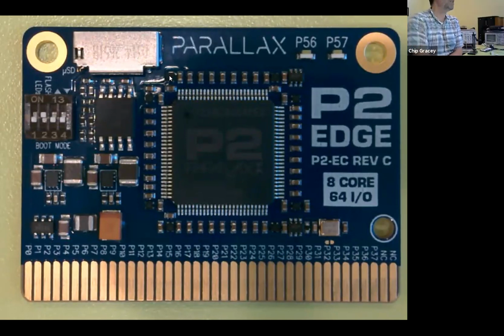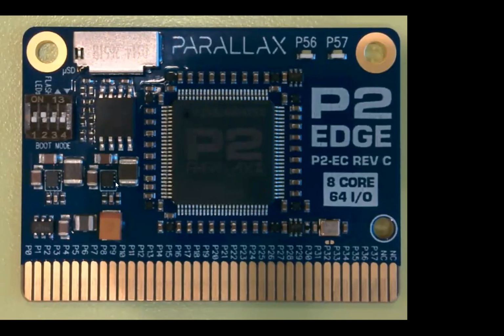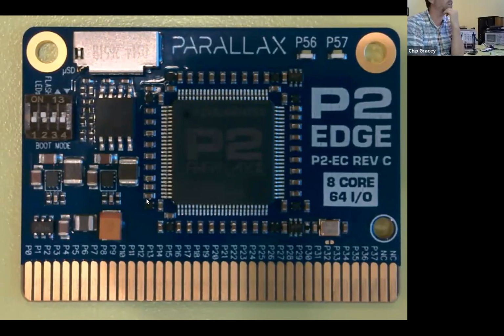So we used to send about 5 volts to these guys, but that was just creating a lot of unnecessary heat and wasting power. So now that we have these switchers here, we can do it a lot more efficiently. So we give it more than enough margin. We're giving it 0.4 volts more than it would need. But I think that differential probably helps the thing react faster under load.